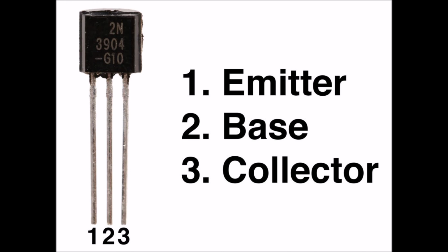Alpha cutoff frequency. The alpha cutoff frequency is determined in terms of the three major contributions: base region transport cutoff, emitter cutoff due to the emitter capacitance, and the collector cutoff due to the base resistance and the collector capacitance. Beta cutoff frequency.